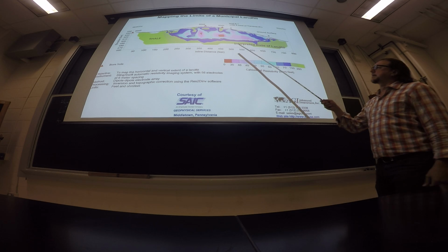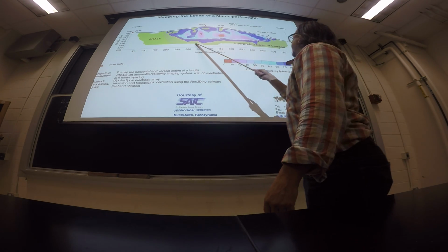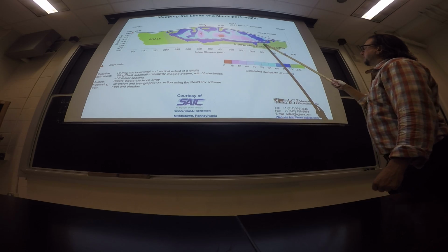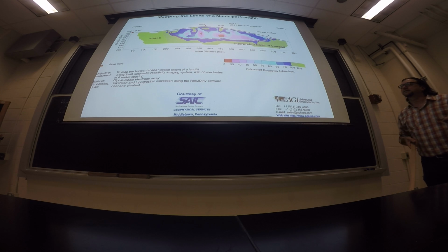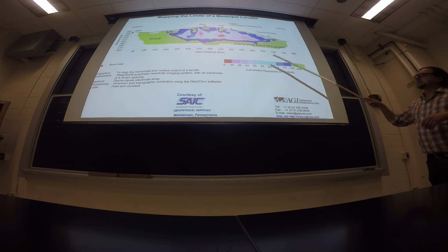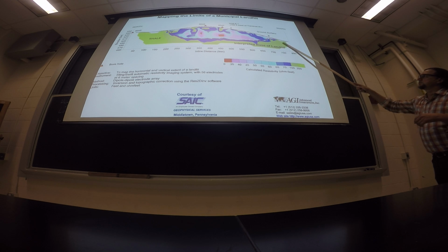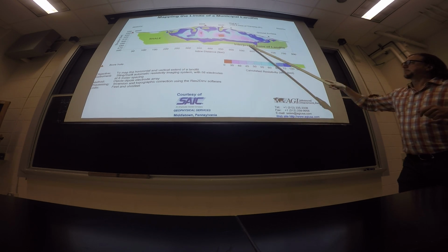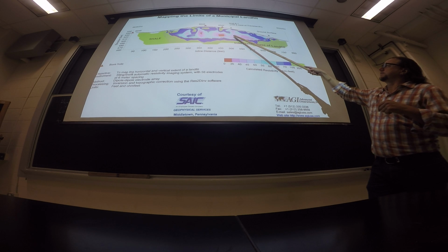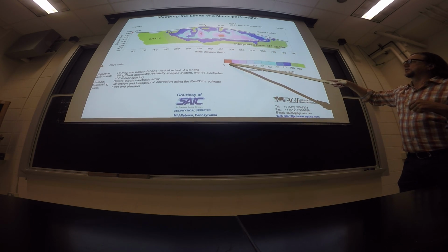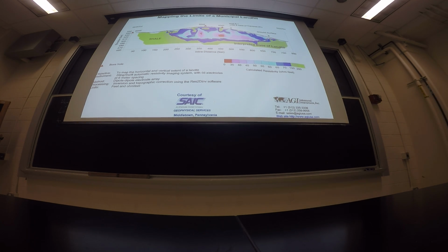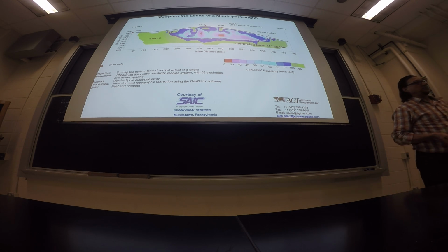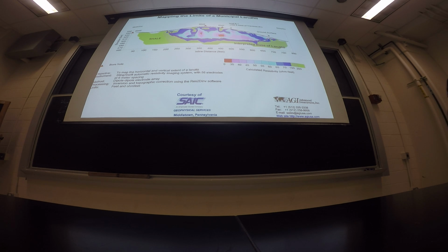And so this is just an example where they use the resistivity just to basically map the bounds of the landfill. This landfill was built into a shale, which was higher resistivity. But you can see how the resistivity goes from 200 ohm meters in the base, below the landfill, down to very low values of below 30 ohm meters. Okay? That's due to the fact you've got conductive materials. Some areas of the landfill might concentrate metals, and so you would see a very, very low resistivity anomaly in that location.